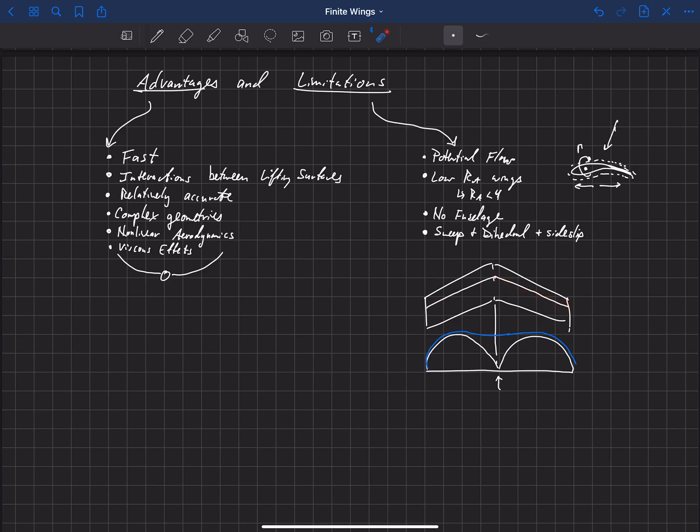But as you get close to this discontinuity here in the center, you have bound vorticity at an angle, and that creates downwash on the opposite side of the wing. And so you can imagine that both of the wings are flying in each other's downwash. That's one way to think of it. You're getting downwash from the velocity induced like that, and as you get close to the center, you have a lot of downwash, and so your angle of attack, or your lift, drops basically to 0 there at that point. Or decreases, I guess I should say.